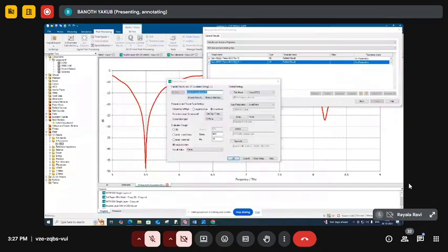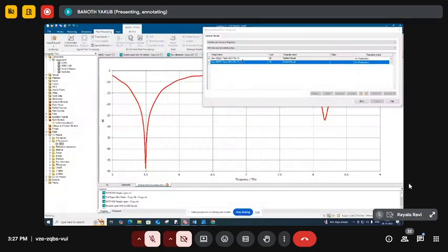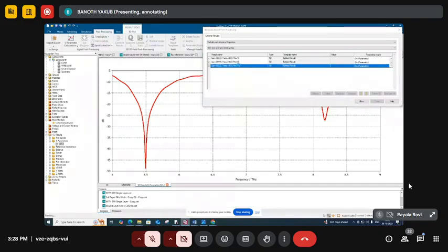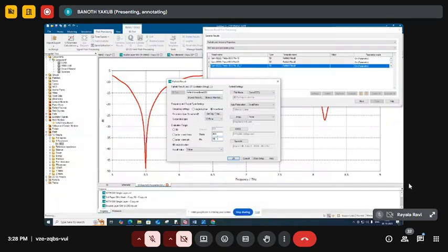So click on that one. For the first option, we can give 10 degrees for the phase angle. Here you can give 20 degrees. Just click OK, and it will be added automatically here after changing that particular phase angle. So phase angle 10 degrees and 20 degrees are changed here. Then go for another duplicate file, and here you can change the phase angle to 30 degrees. So you can see a 10 degree variation, up to 150 degrees.